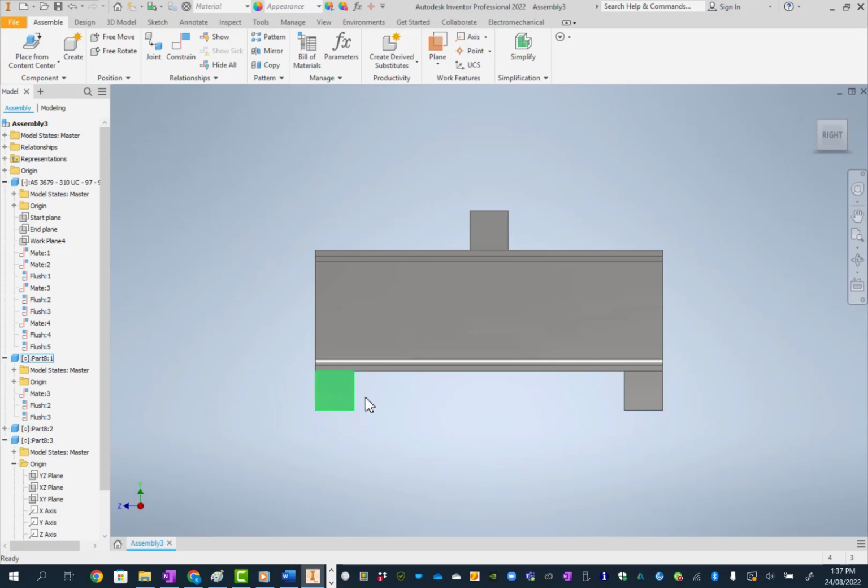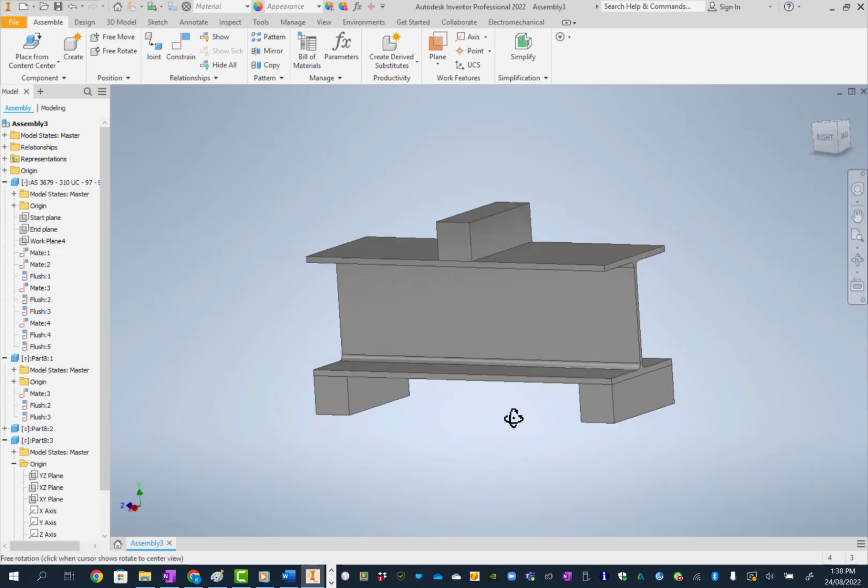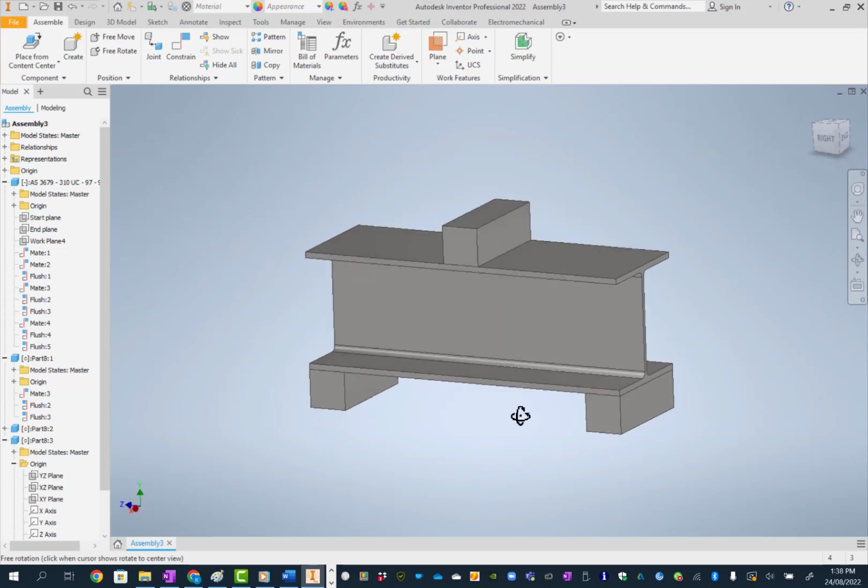Those are like the supports we see in our diagrams. And I'm going to load it on top here. I've just put this block on top, so I've got something to load onto. You don't really see shear if you've got a long beam that's not very deep. The time when you see shear is when you've got loads very close together and a pretty deep beam. Then you'll start to see shear becoming critical, so it's more important than the bending effects that we'll talk about next.